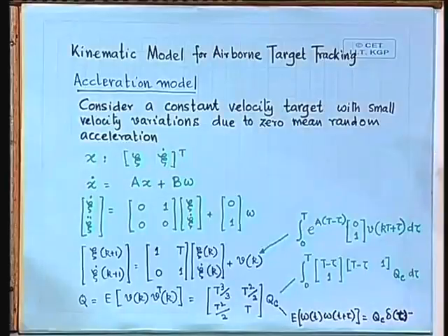Now, it may appear to you that if you have position, you differentiate position, you will get velocity, there is no problem. But it turns out that if you take such a naive approach, you land nowhere. You will get absolutely no estimate of velocity at all if you get a noisy measurement of position and try to directly differentiate it. So you need to do more sophisticated estimation, which is by Kalman filter, and when we see our numerical simulation, this will be borne out.